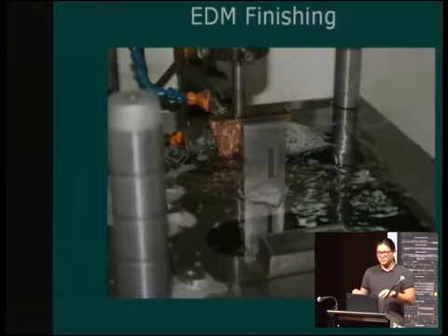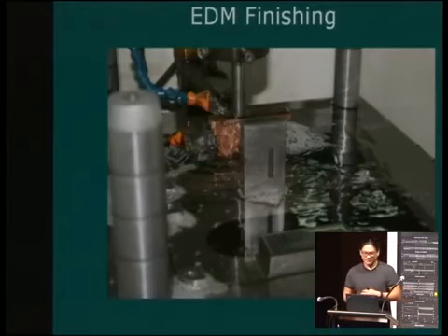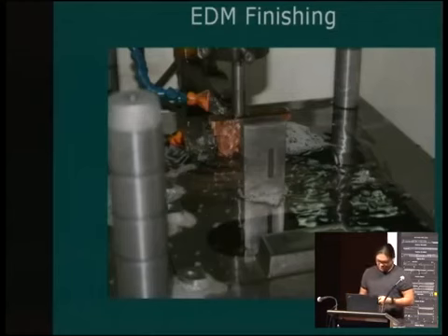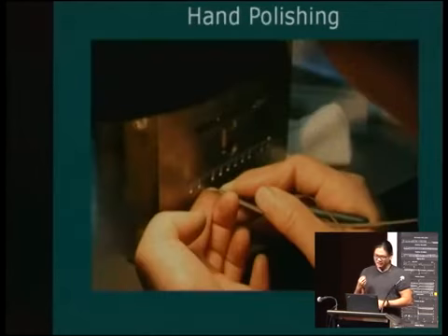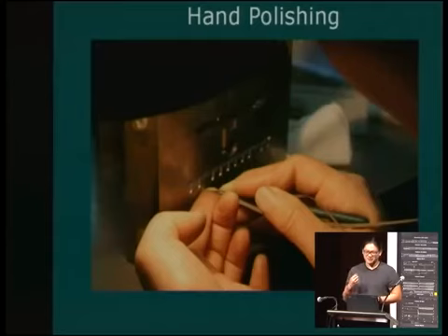It's a very, very slow process. It takes maybe 8 to 10 hours to put one feature in. But the finish is extremely high quality. It's down to half a micron precision. So tooling is a very, very time-consuming and very expensive process.